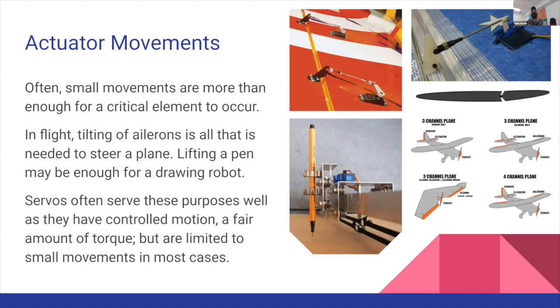And so this is a good example to think about here, where you've got a little tiny hobby servo mounted, and your pen on a plotter just has to move up and down, not very far, and it's not a lot of weight. It just needs to move enough that it's writing on the paper or not writing on the paper. And so in that case, you don't need a full stepper motor. You can use a little actuator that'll just act and unact.